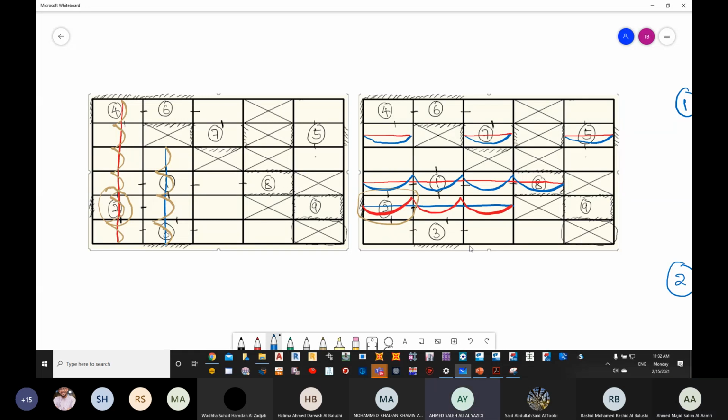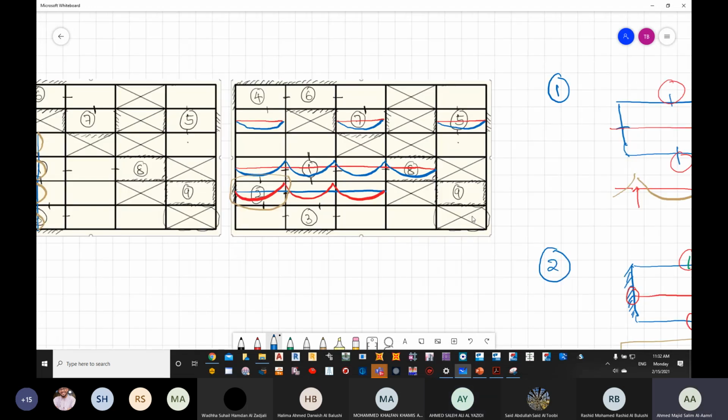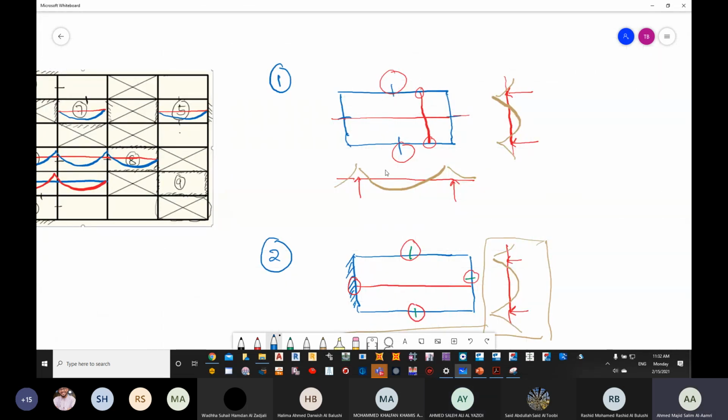So that means Y and X, we should draw, right? If you ask for all the bending moments, we should draw Y and X. Yeah, both. If it's two-way, both, of course. That's why I'm drawing for each and every case, whatever I have finished, I'm drawing 2, because this is assumed to be a two-way slab now. If it's a one-way slab, it's only one side drawing, as we said.